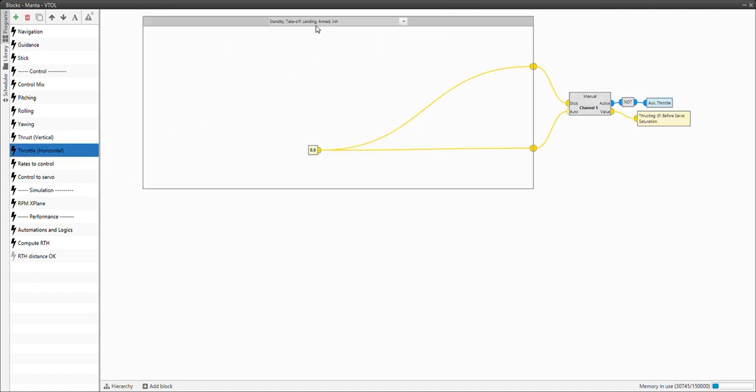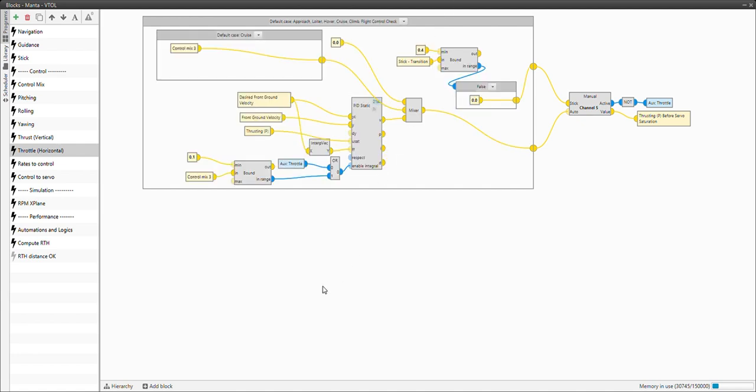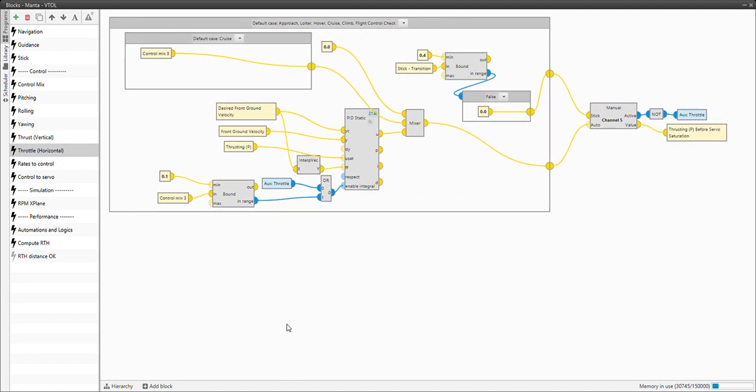And for what concerns the horizontal throttle, I just want to remind that this is a multicopter plus a fixed wing, because it's an eVTOL, so it can convert. So we need to divide the logic for the throttle into the vertical and the horizontal component.